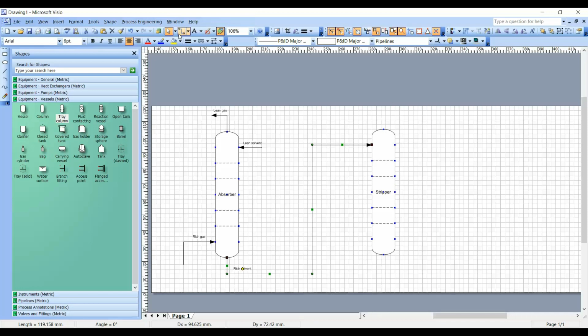What we do here is use hot steam or any other liquid. In this case we can call it the hot steam or recovery stream that contacts the solvent, and then it evaporates the material that we are interested in, which is the gasoline. Let's say it's gasoline, and then we will end up with some lean solvent here, which we will take and move to the absorption column, and this is the system. But there are some other details here just to make sure that the unit is efficient.